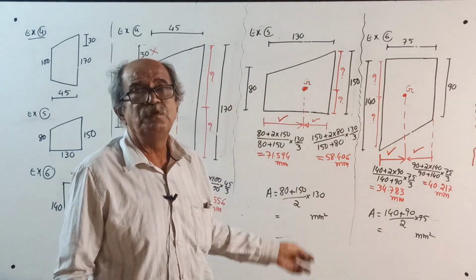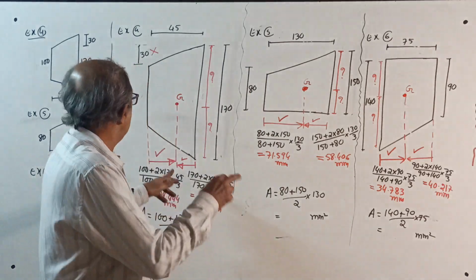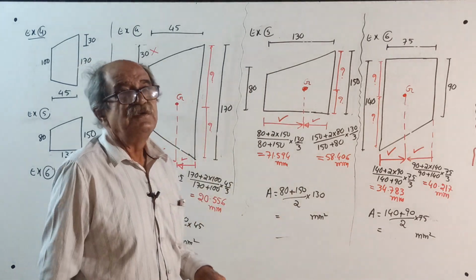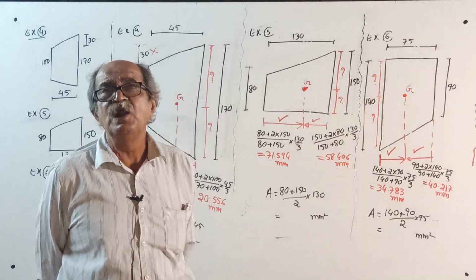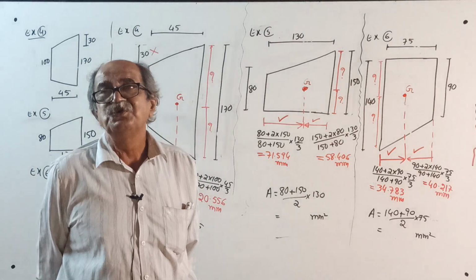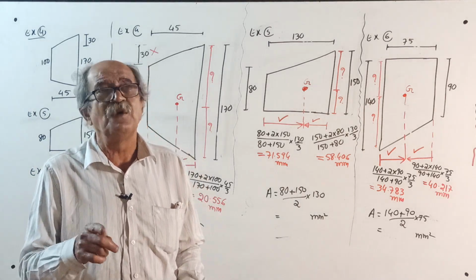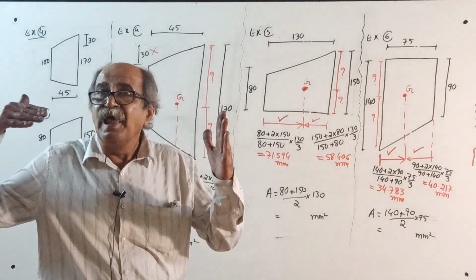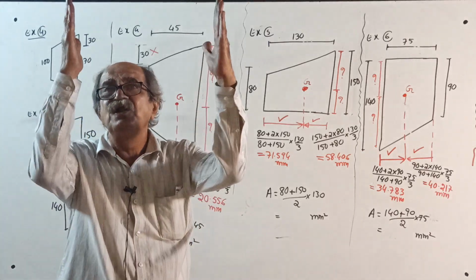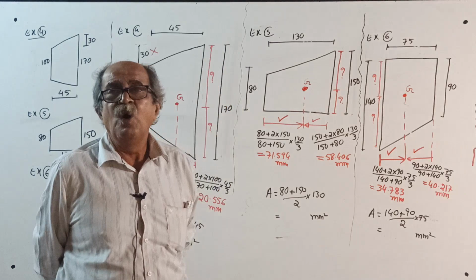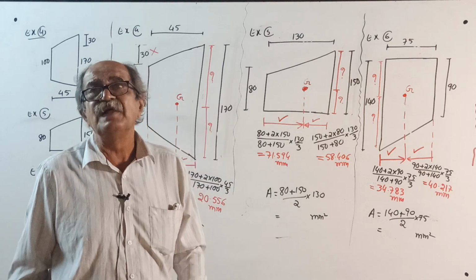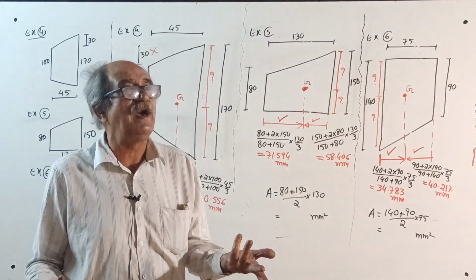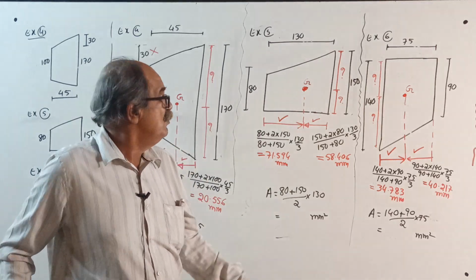So next class is more powerful. This is very, very powerful because usually in structural engineering, when a trapezoidal load comes, remember, you always require the distance of the centroid along the base or one of the parallel sides. So in all the bending moment calculations, the standard expression is useful. The other centroid distance is not required. But anyway, we will complete.